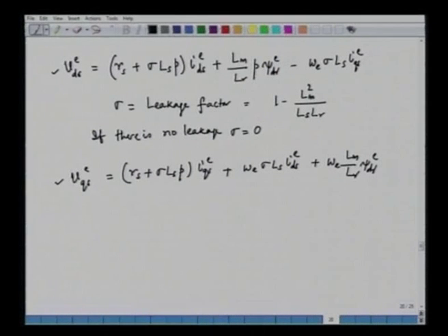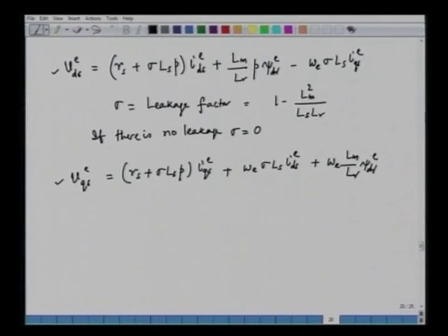So, it means if we know IDS and IQS, or IDAC and IQAC, we can evaluate what VDAC and VQAC are, which you can show in the form of a block diagram. So, this basically will translate the currents into the voltages, which will be useful for controlling a voltage source inverter in the voltage control mode. So, we will see how we can have that in the form of a block diagram. So, this is shown in the following fashion.